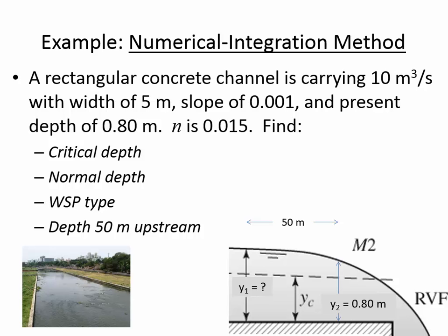No, it's when you've got a mild slope, but the flow depth is less than the critical depth, but then you'd have a hydraulic jump. So if you had temporarily supercritical flow on a mild slope, that's what will support a hydraulic jump.